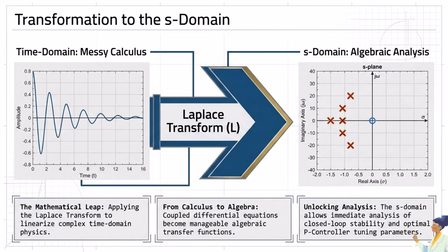By working in the S-domain, we can directly analyze closed-loop stability, map out the poles on an S-plane, and calculate the optimal tuning parameters for our P-controller. We shift from observing physics to engineering a stable system.